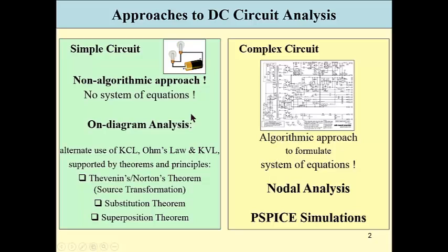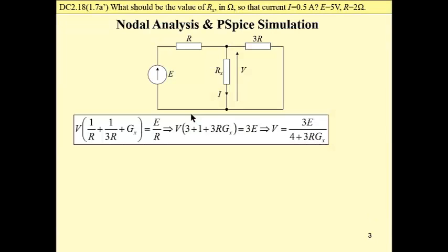Thevenin's or Norton's theorem, substitution theorem, and superposition theorem. For a complex circuit, however, we have to apply nodal analysis or computer simulations, PSpice simulations. So let me start with a nodal analysis approach. For this circuit we have to write down a nodal equation, a single equation like here.